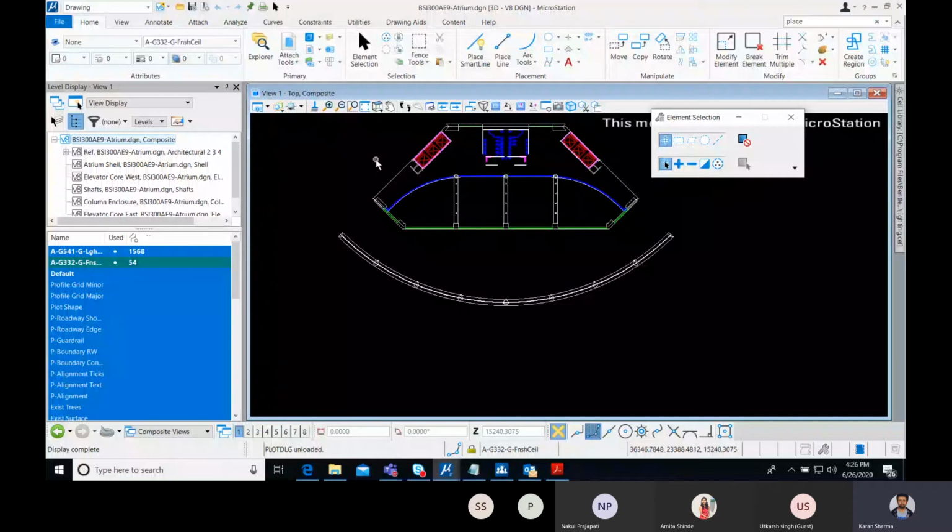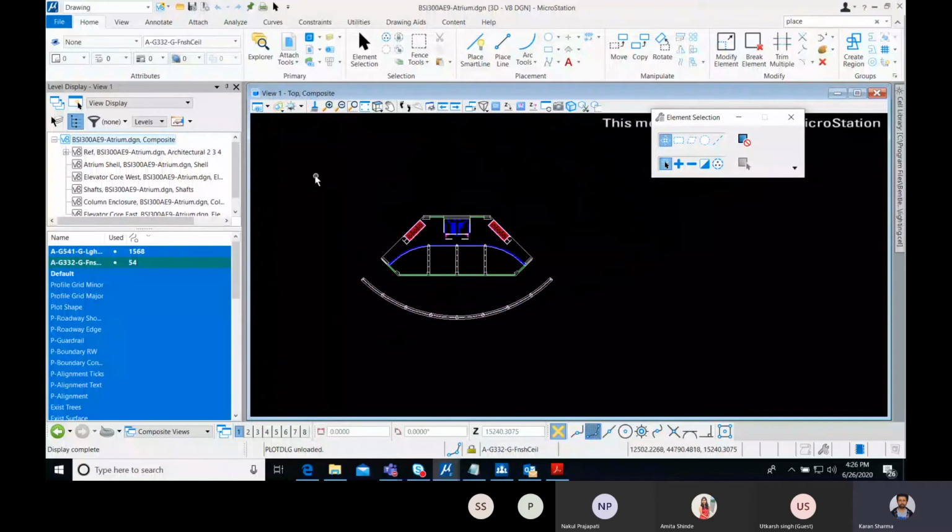I'll change the rotation from my view attributes, view bar here, to top view maybe. Okay. Here in top view, I'll attach a border in itself. Now remember, this is a full scale drawing, right? And the border is according to a paper size. So we will have to increase the size of our border.